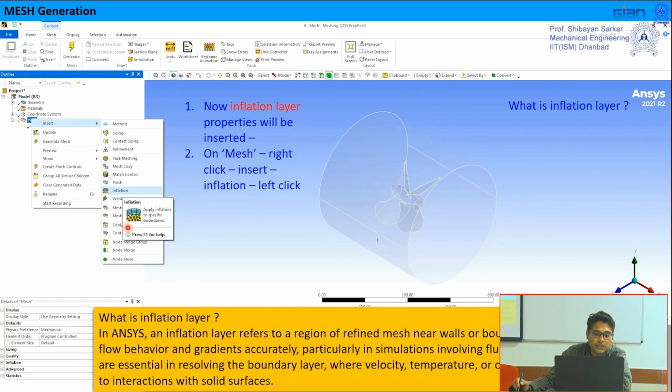If you see this figure, you can see this yellow one, I am assuming, this is the solid body and the fluid is traveling, and I am creating multiple layers. Basically these multiple layers will enable very fine calculation, and I need to give this especially to this geometry, as well as to the computational domain when I will be representing a solid surface, channel surface to the computational domain. That part I will give later. Right now I am giving it to this rotor.